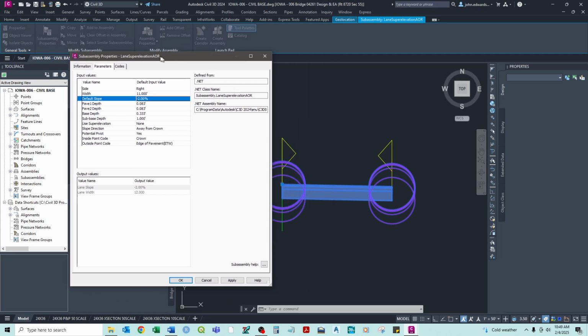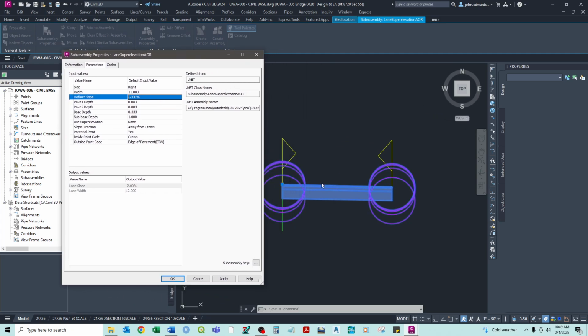But what that does is, you set that, so that's going to be the full depth of everything you're putting in. And we'll talk about this in the next video, but by the end you will have a surface that has the top of your corridor, so the top of your roadway, but also the datum, the bottom, because that's the point at which they need to cut down to or fill up to before you put your surface materials for your roadway.